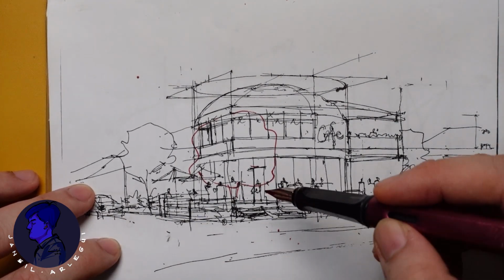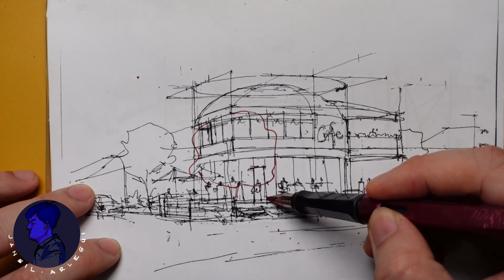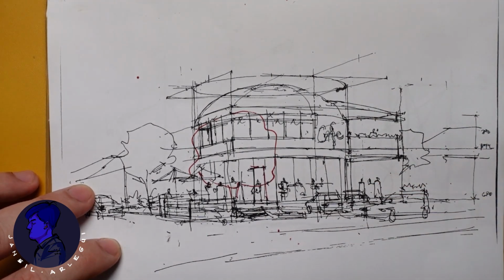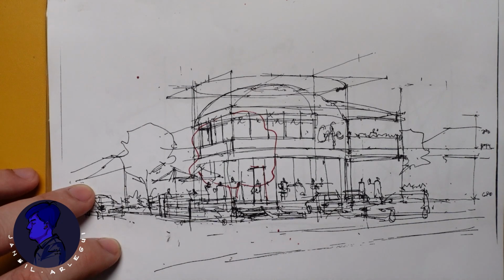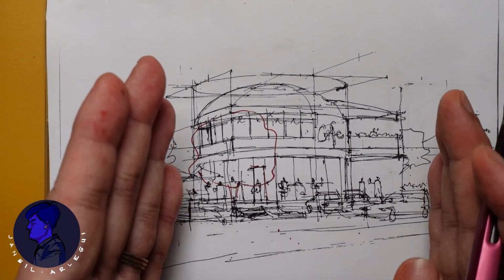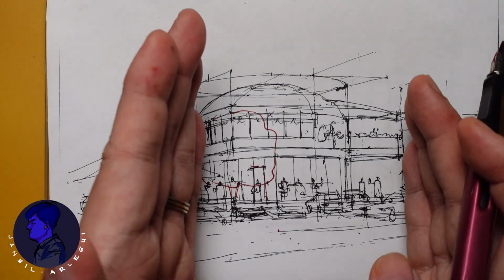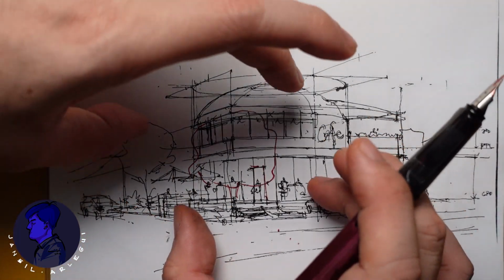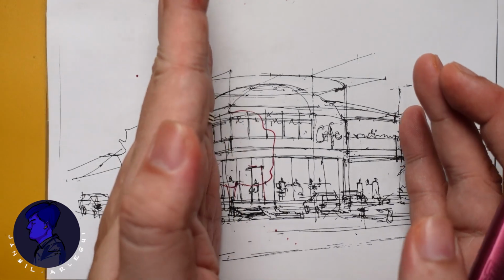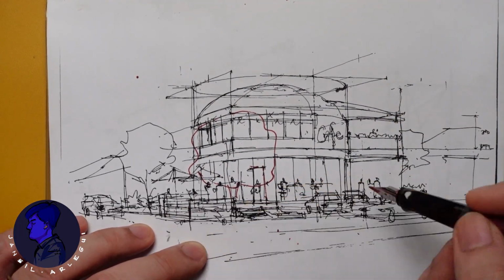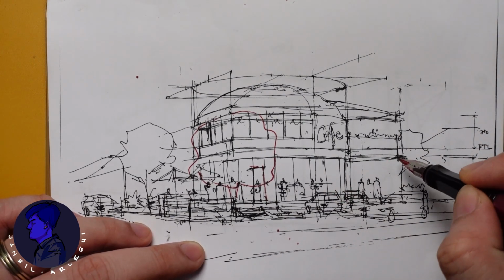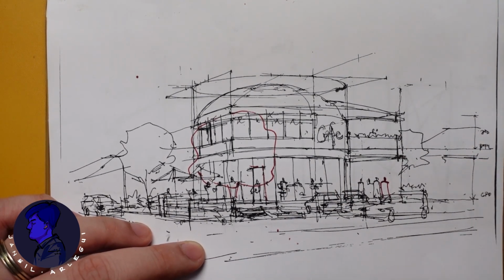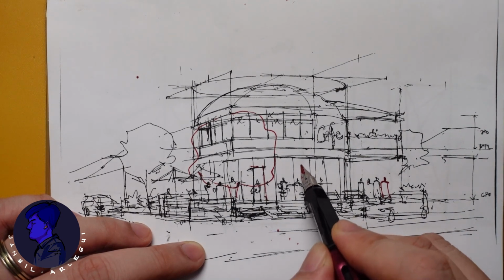When you're trying to draw a perspective, always show, of course, where the front door is. Don't draw a perspective view where you don't see the front door if you're only going to do one perspective drawing. Currently, I haven't framed this properly. It's supposed to be shifted roughly here for the focal point, the 1/3 rule. But at this stage, this is still a work in progress, and it's also a good stage for you to sketch, design, or iterate more.